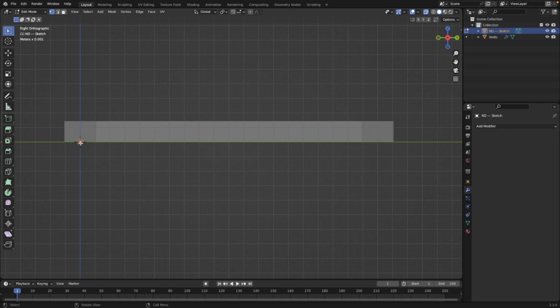So what I would like for this vent to do from the side view is I want to extrude it kind of up this way so we get that angled slat. I don't want it to go all the way up. I'm gonna hold down Control so that it snaps to the grid. Actually, no, I'm not. I'm just gonna freeform it. So I'm gonna go up at an angle about like this. I don't want it to go all the way to the top of the frame, so I'm gonna leave it right about here. Then we're gonna extrude it only in the Y axis.